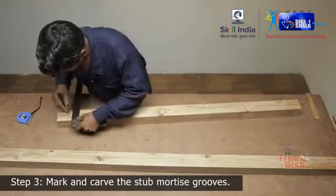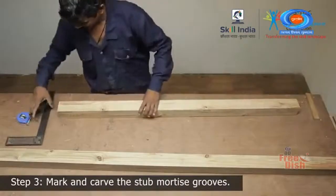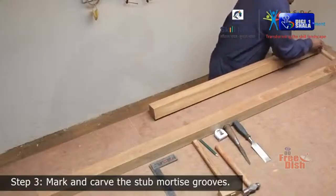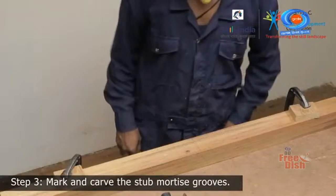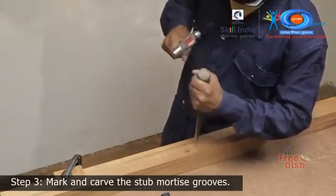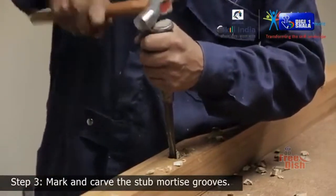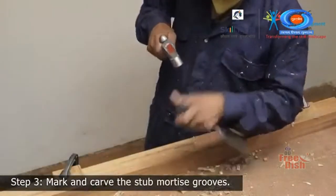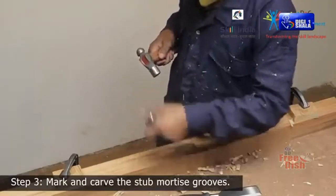Now, mark the width for the stub mortise grooves on all the positions on both the sides of the stud members. Secure the wooden piece firmly on the workbench with a G-clamp. Chisel out the stub mortise in the middle. Chisel down halfway through the mortise hole and clear out all the debris from inside. Similarly, carve out the stub mortise on all the stud members.